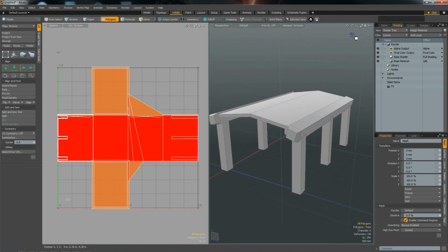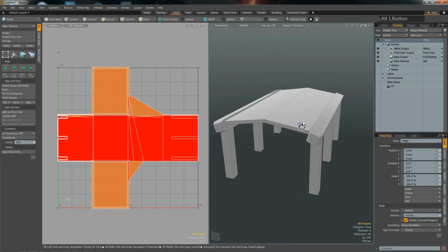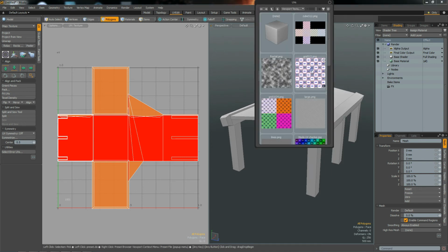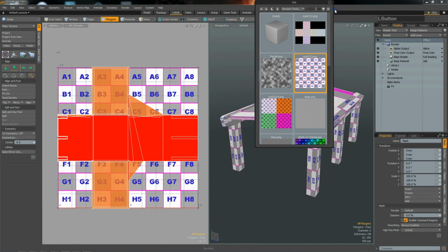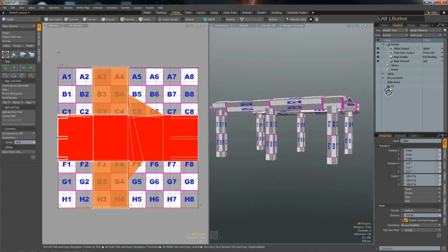better overview of things, first I'm going here in the viewport and deactivate my work plane. I don't need that. And I don't want my grid. I don't need that. But what I do want for my UV maps here is a viewport texture with UV maps, so I can see a little bit better what's going on. Okay.